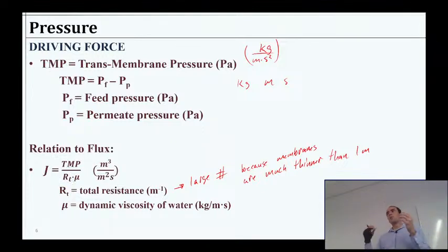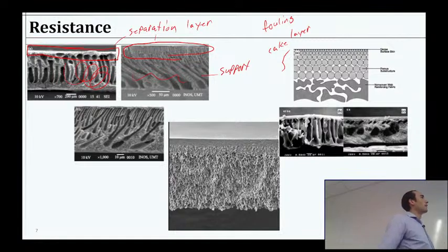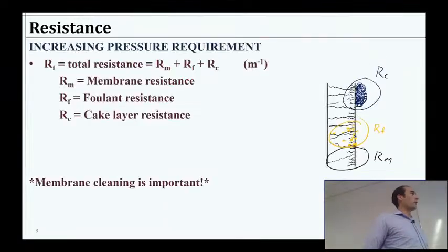That's also why really fine membranes for removing really, really small stuff, they just inherently have a lot of resistance and therefore require a lot of pressure. And the inverse is true. Also, you tend to get very little flux out of them. So both of those are kind of happening at the same time. A bit of a trade-off there. And part of that trade-off, by the way, is what we make the membranes out of, they can only handle so much pressure. So even if we could pressurize a system really, really strong to meet the flow rate that we really wanted, chances are the membrane itself can only handle so much. So at some point we have to just settle for less flux.